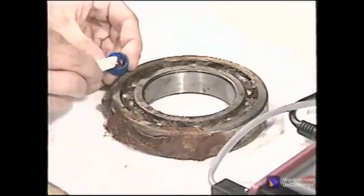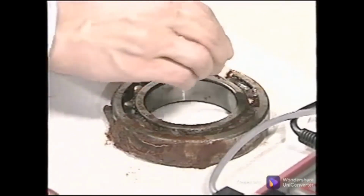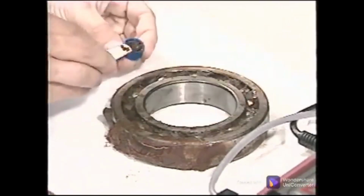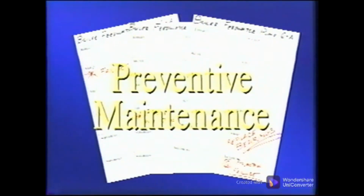Analysis of oil or lube samples from the failure is really post-mortem analysis and will have excessive wear particles, contaminants, and may be degraded due to excessive heat. The second maintenance philosophy avoids these catastrophic failures by looking at the machine from a historical perspective. If it tends to fail every 18 to 20 months, then replace the bearings every 12 to 14 months to prevent a catastrophic failure. This philosophy is called preventive maintenance. Oil analysis programs and preventive maintenance plants tend to only replace the oil at calendar intervals, with the lab reports of the oil condition really having no effect on the maintenance program.